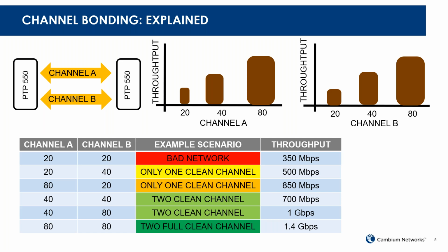So in real deployment, the RF conditions differ, and also the available channels on each spectrum differ. For example, 5.8 has 125 megahertz of spectrum available. You can't fit two of the 80 megahertz in there because you can't overlap the channels. So you have to do one. Let's say you choose one of the 80 megahertz in 5.8 gigahertz. If you want to do another 80, you have to find it in 5.1, 5.2, or 5.4 somewhere. So there is a selection about where you want to be.